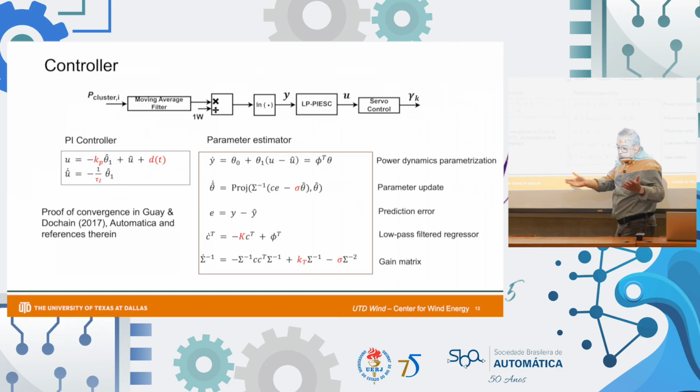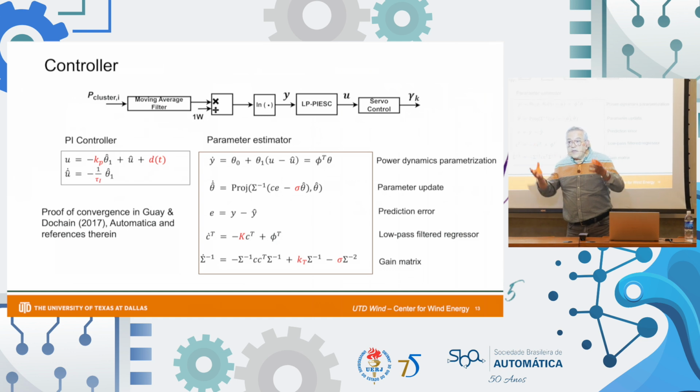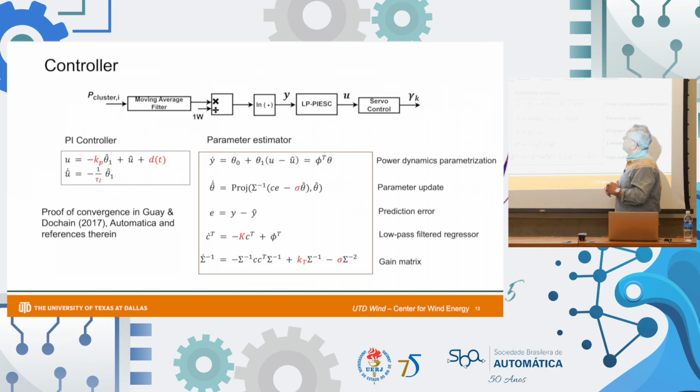The argument of the log should be a non-dimensional quantity, and that's something that sometimes we don't teach in controls courses, the significance of normalizing everything before you do the controller, and then bringing those scale factors back into the controller. In this case, it's 1, so it means nothing, but it could be different. Then we apply the log, then we apply the PI-ESC, and then we command the gamma.